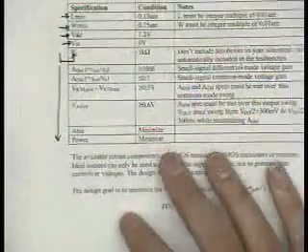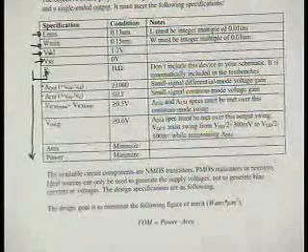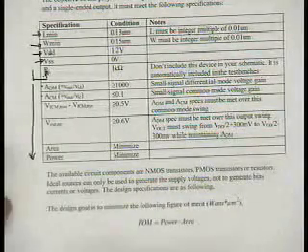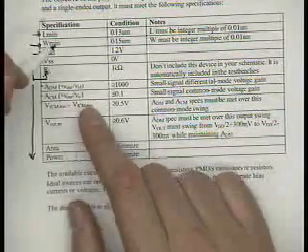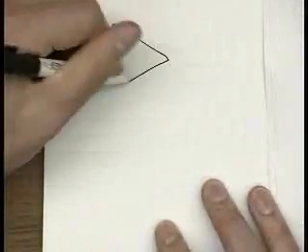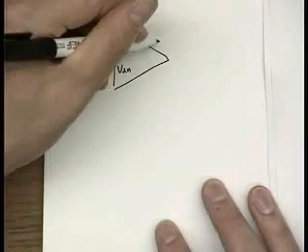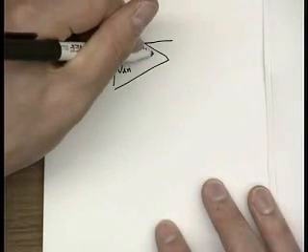Okay? So there are two specs of primary importance: differential mode gain and common mode gain. Okay? And the differential mode gain is defined as Vout over the input differential voltage. So it's a little different from what Bob mentioned in class, where you have VIP. What Bob had was differential in, differential out.